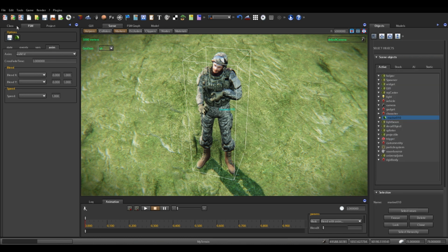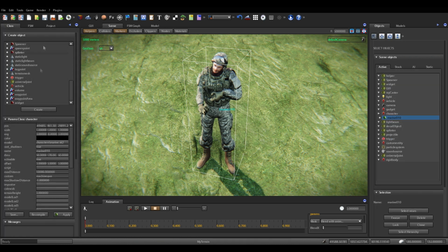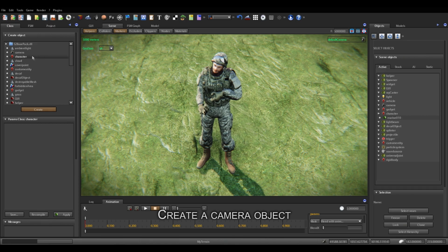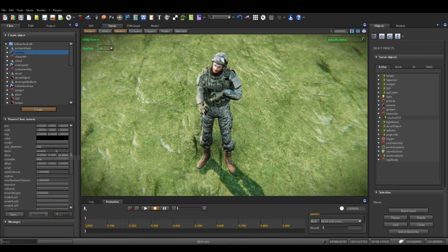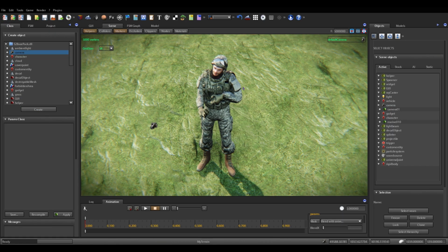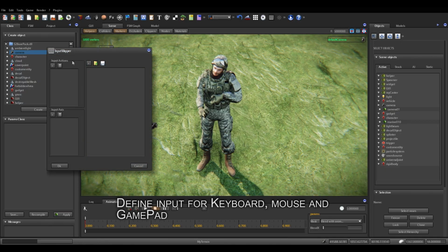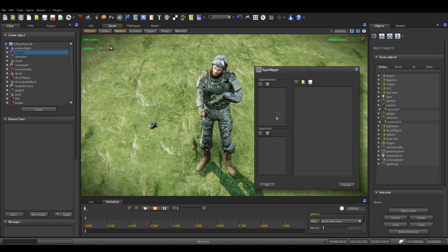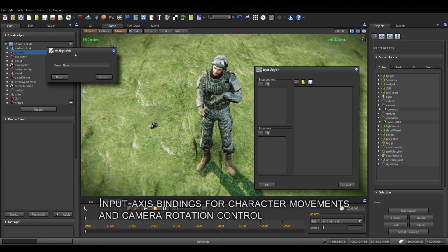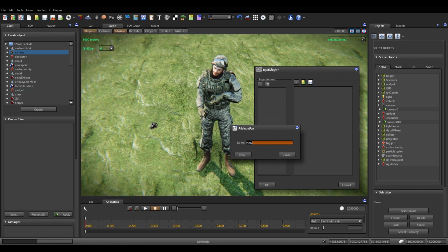Now we create a new camera object, selecting camera from the creation panel and click the create button. We see camera object parameters. In our case, we make camera activable. That means camera be activated at start. By clicking in scene, camera object will be placed. And then we again click on the create button for exiting from creation phase.